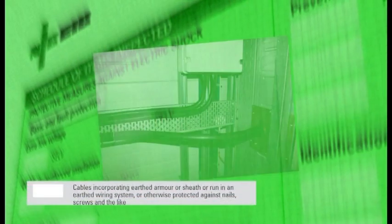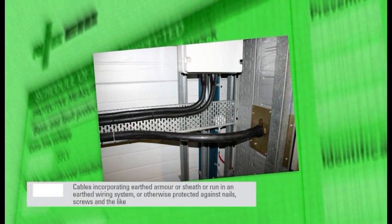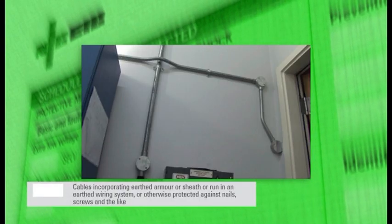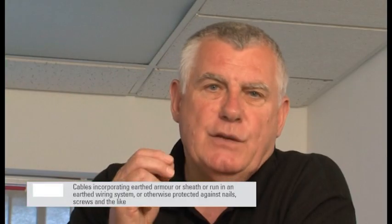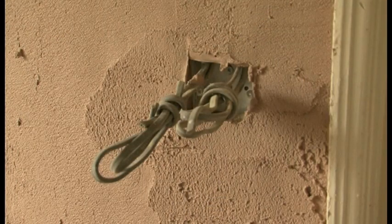The next box requires the inspector to check that the wiring system incorporates an earthed armour or sheath, or is mechanically protected against the penetration of nails, screws or the like. And it's worth mentioning here that metal capping will not provide that degree of protection. Metal capping is there to protect the cable from the plasterer's trowel.